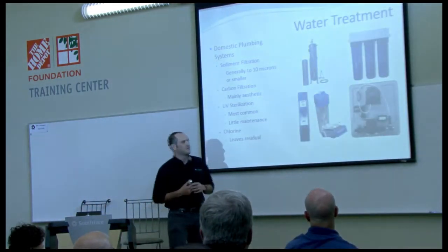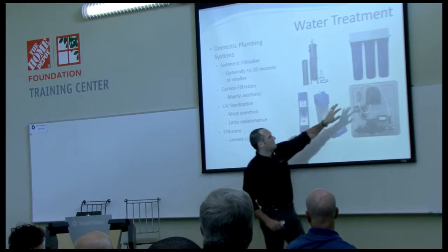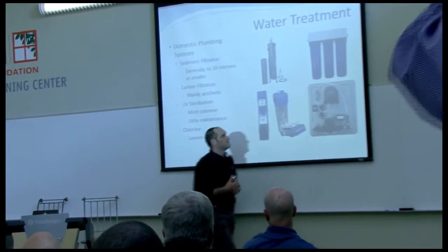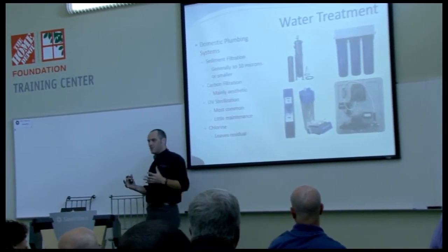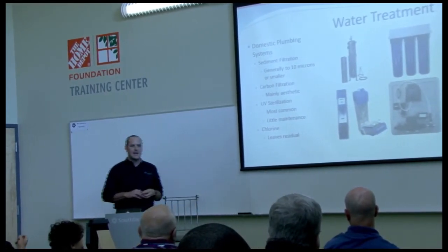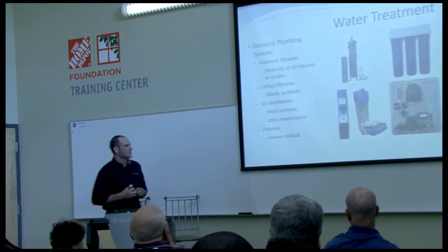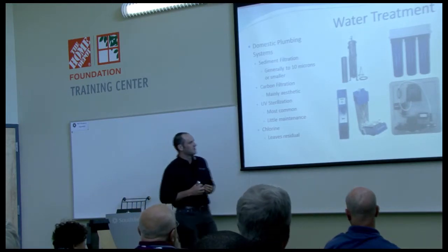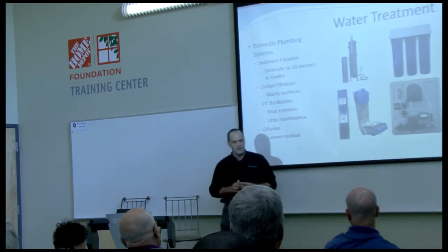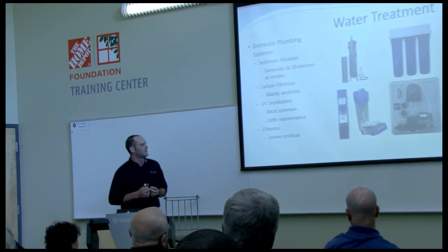For you to utilize a UV sterilizer, you have to filter down to 5 microns first. So typically you'll see a filter bank like this with maybe a 20 micron, a 5 micron, and maybe a 1 micron carbon filter, followed by a UV light. We've done many potable systems using just that technology, and gotten really high water quality. In most cases, higher than the municipal water available at the source. All you have to do is change your filter elements periodically, and change the UV bulb once a year. So that's probably the most common. That's becoming the industry standard for disinfection.